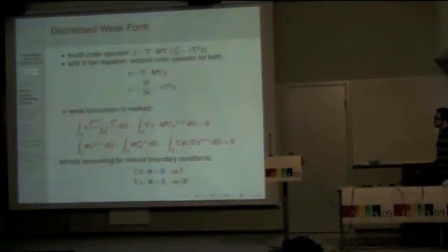Basically, this is the evaluation of the time derivative of c, which is the concentration, the mass fraction of carbon, and this is the term evaluated at an intermediate point weighted by this parameter, which is called theta here. This is the second equation. In this way we could recover both boundary conditions.